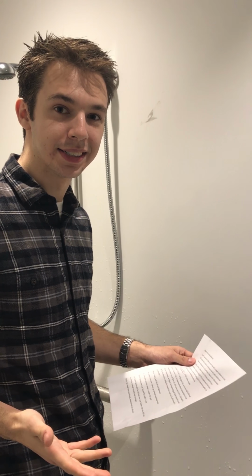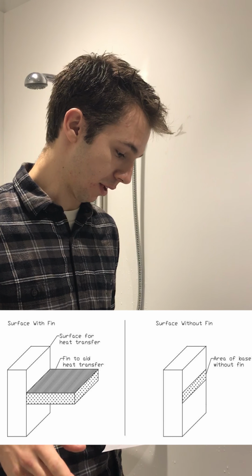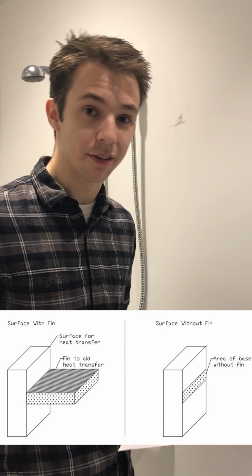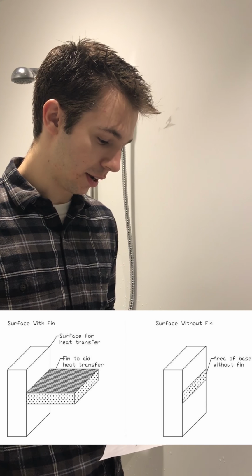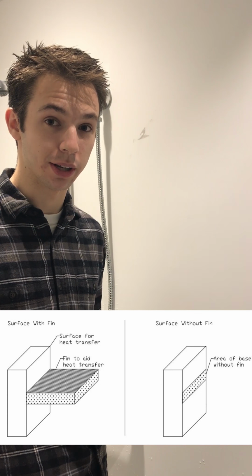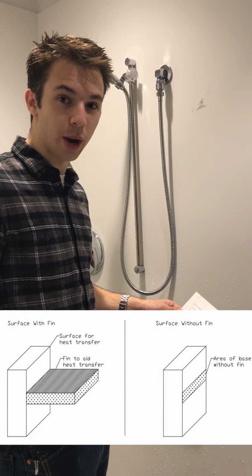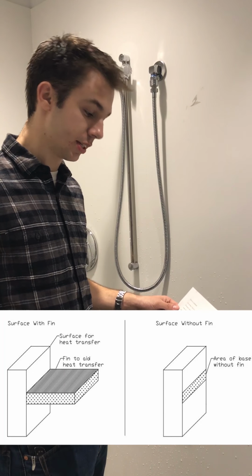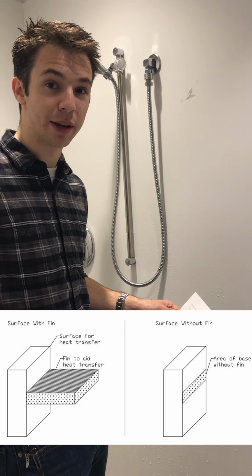Alright, so let's go back and consider that fin in the flue shaft and its usefulness to the system. We generally do this by comparing the ratio of heat transfer with the fin compared to the heat transfer that occurs without the fin. Fin performance is based on a variety of factors, including length, volume, thermal conductivity of the material used in the fin, and the thermal properties of the surrounding fluid. In our case, this is going to be the thermal properties of carbon dioxide and water created by the combustion reaction. We can use equations derived specifically for different situations of fins to calculate the heat transfer through a fin. For more about these equations, please refer to the supplementary document to this video.